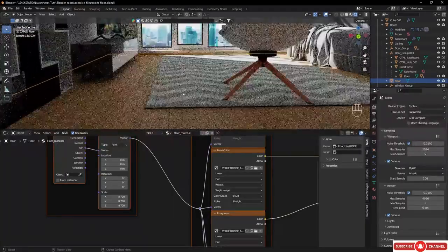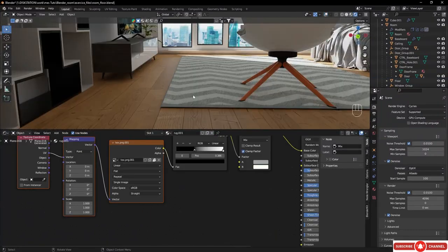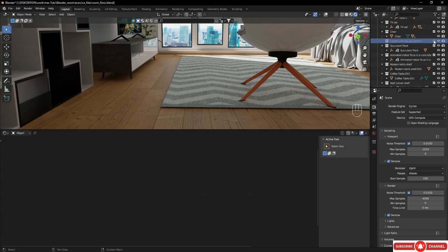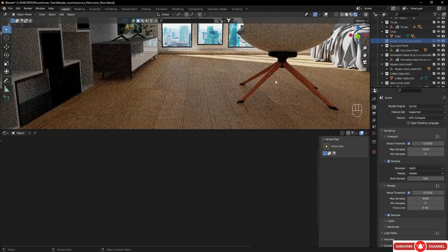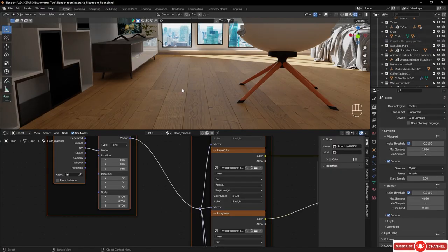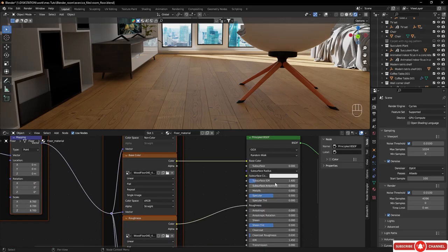So if I want to tweak more the material, I'm going to zoom in and maybe look this way. And also, just for this, I'm going to turn off the overlay, take here our carpet. So I just clicked, then period on the numpad key. I'm going to find here our carpet with zigzag pattern. I'm just going to unload so that we can see the whole floor. And if we want to tweak it to make it more reflective, we just have to play a little with that. So what we could do, if you want to make it more reflective, is already increase the specular to 1.